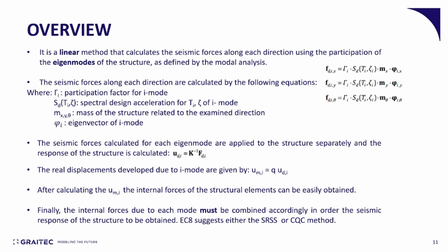The real displacement developed due to this I mode, due to these seismic loads that come from the I mode, is given by this equation. And after calculating the U, the real U that corresponds to the I mode, the internal forces of the structural elements can be easily obtained.